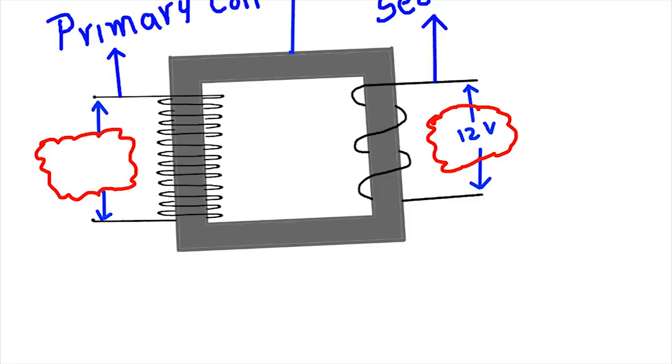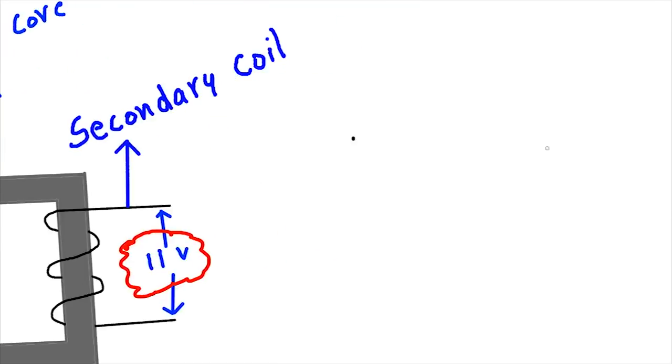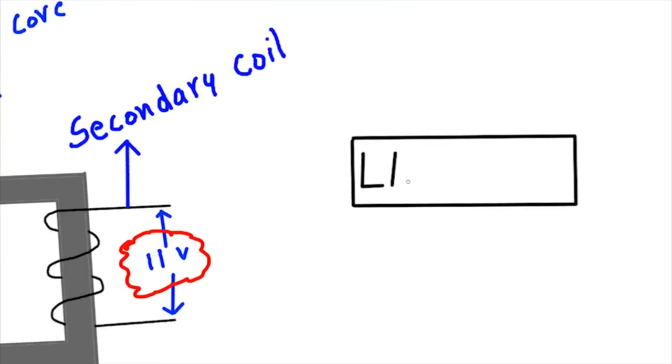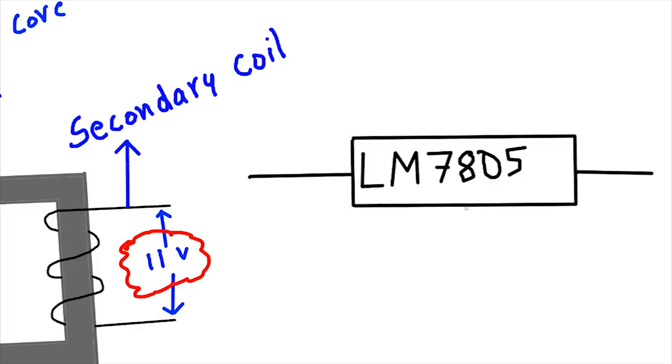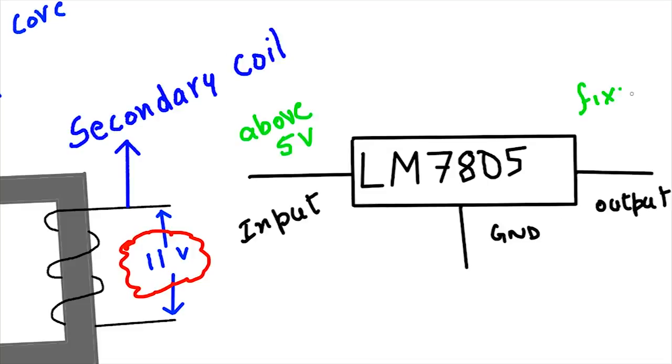There are chances that your source voltage varies whenever there is a voltage fluctuation in the power plant or for many other reasons. This is the reason why we need a transformer of slightly higher range than required, so that when the source voltage comes down to a certain level, the transformer output may still remain at a voltage higher than actually required, so that the input of the voltage regulator always remains higher than its output.